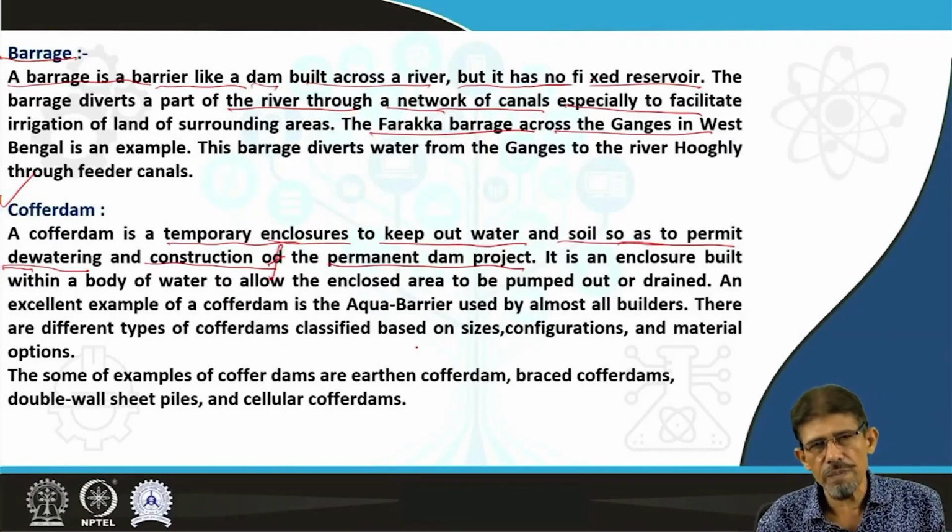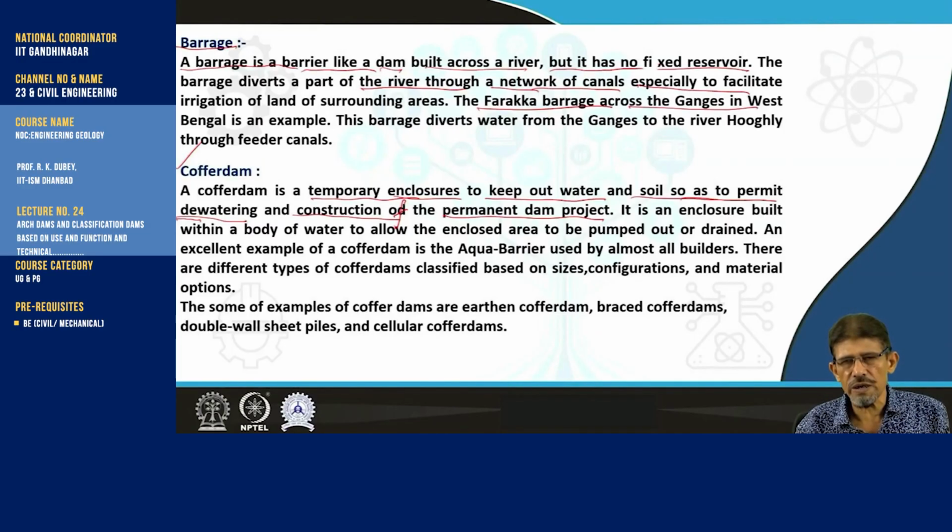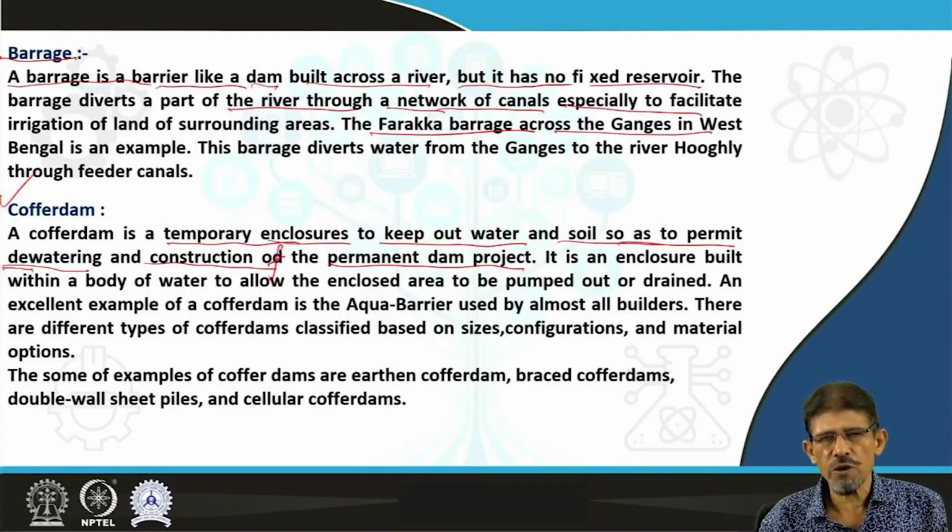This type of dam we construct at a very initial stage to facilitate construction of the main project by clearing the site through diversion of the channel. It is also utilized for transportation of material, movement of the persons working for the main project, and other facilities, machines and others.